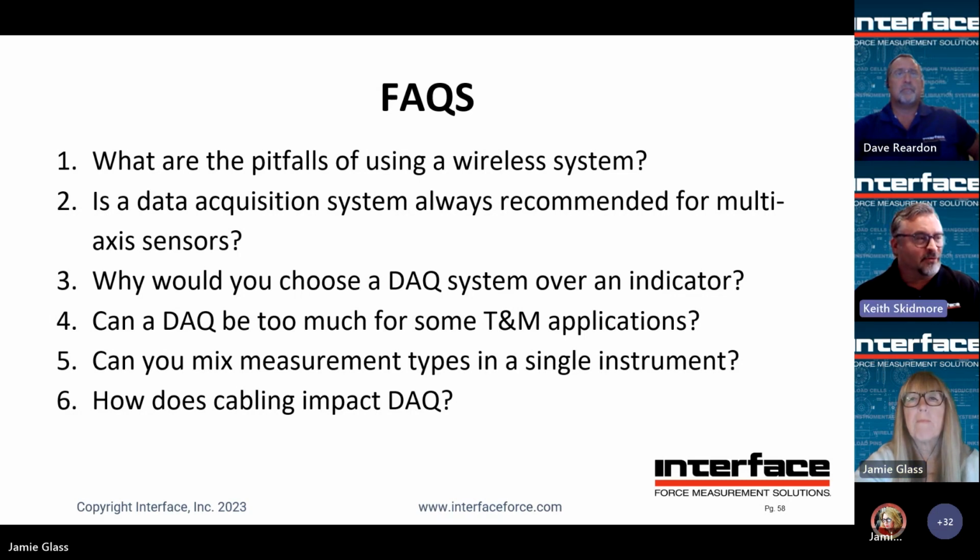We have a separate manual which is available. It's pretty simple. There's digital IOs on these devices, and they can be set for master slave arrangements, and then you basically hook up the DIO on one to the DIO on another, and they clock the two systems together, or multiple systems together via the same methodology.